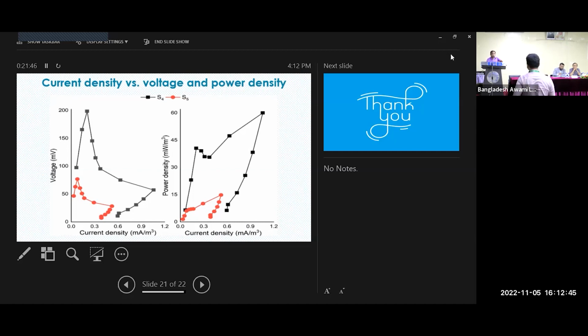Actually, we introduced earthworm because it has burrowing activities. It will create cracks, and it will additionally facilitate the transmission of oxygen inside the media. But another source of oxygen is the plant in the wetland system, because these Phragmites plant roots release oxygen inside the media. So that is a source. And also during the drying process, when the media is dry, atmospheric oxygen will enter inside the media.